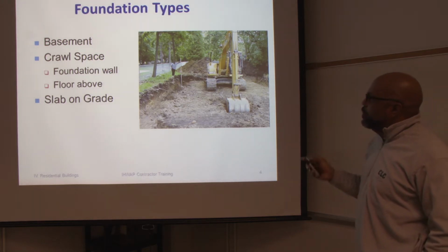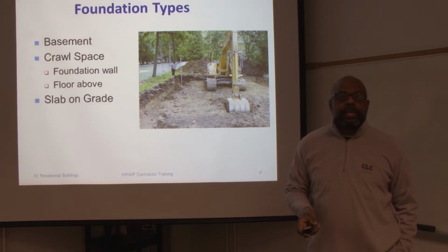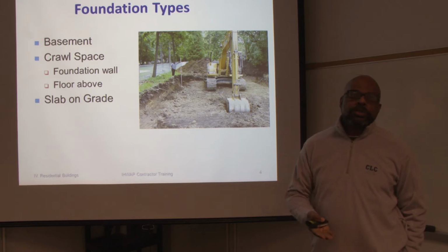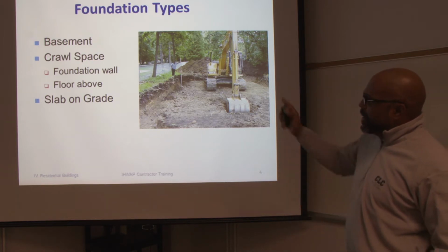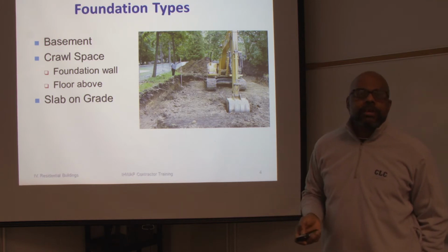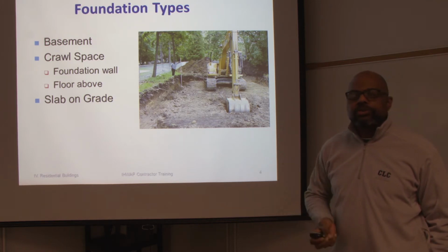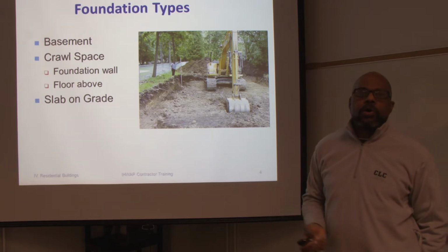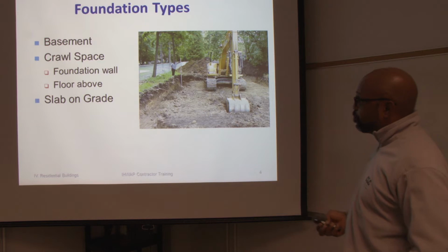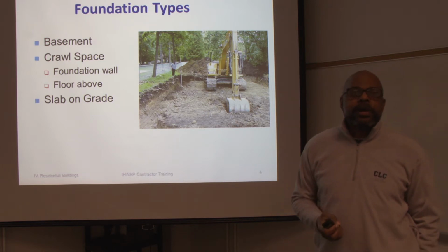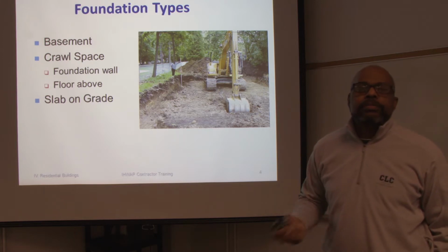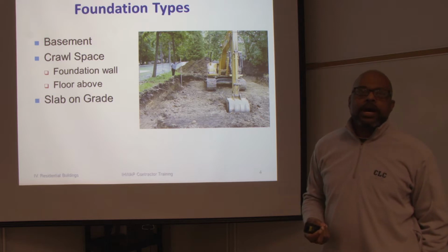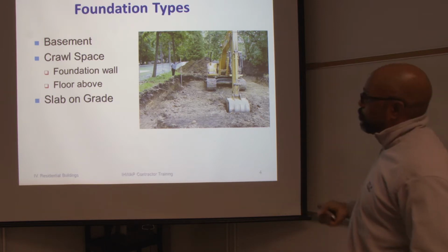Basically, a foundation is what holds the house up. It's what the wood framing for the walls sits on, and it has to be large enough and strong enough to support the complete structure of a house. Different things you may find: basements are common in the Midwest because the temperatures get very low. They use basements to keep cold floors out of the living space. Crawl spaces are another way. It's not a livable space, but it's a space below the house, and that's where they can put mechanicals, plumbing, or electrical fixtures or conduits for the structure.